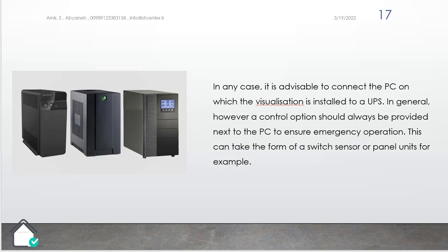In any case, it is advisable to connect the PC on which the visualization is installed to the UPS. So always you should connect the server, mini server, the monitoring system to the UPS. And I should say that some nice manufacturers in KNX provide us the redundancy in server and mini server. Okay, so you have the redundant server or mini server, and also you connect the redundant and the main server also to the UPS.